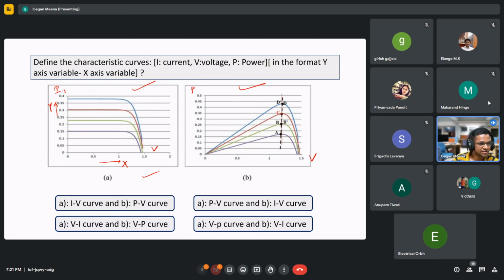So this is the short circuit current, and this is the open circuit voltage VOC. So we have maximum current, short circuit current, and maximum voltage at VOC, open circuit voltage. Then why don't we have maximum power at these two points? It's very easy, but still, although we have maximum current available and we have the maximum voltage point, we don't have maximum power available at these two points.